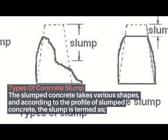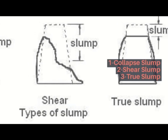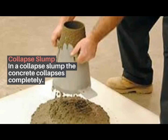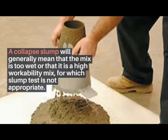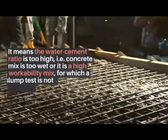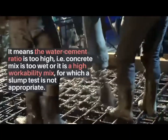Types of concrete slump. The slumped concrete takes various shapes, and according to the profile of the slumped concrete, the slump is termed as 1. Collapse slump, 2. Shear slump, 3. True slump. Collapse slump. In a collapse slump, the concrete collapses completely. A collapse slump will generally mean that the mix is too wet or that it is a high workability mix, for which a slump test is not appropriate. It means the water-cement ratio is too high, i.e. the concrete mix is too wet, or it is a high workability mix, for which a slump test is not appropriate.